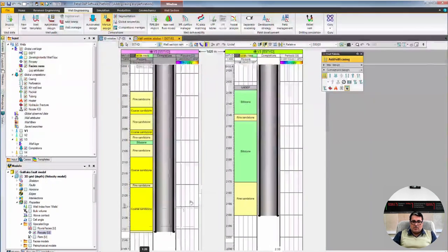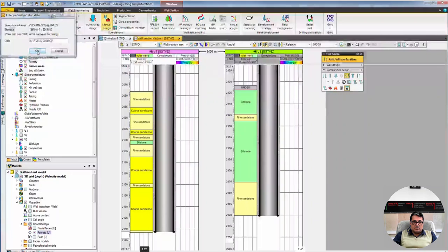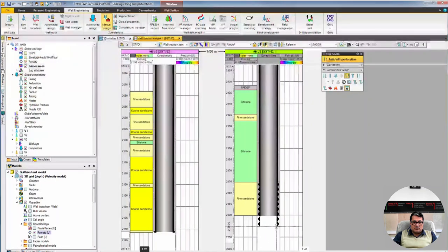So we can go ahead and add in the tubing liner, but in this instance we'll go ahead and add in our perforation straight away, and then we can select a position on the well, again specify that start date, and then we can interactively change. So we'll go ahead and choose to perforate only this bottom section of this well.